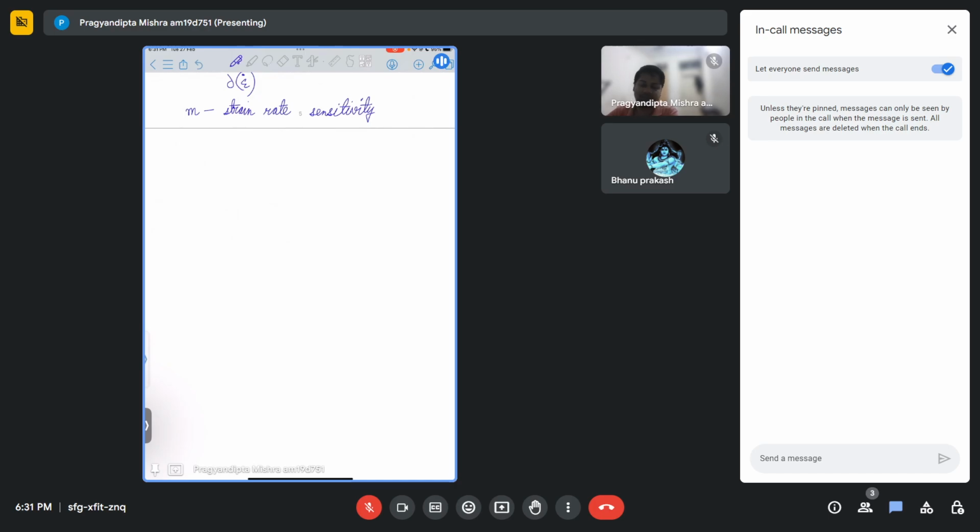If you want to write this in relationship form, this would be sigma is equal to c times epsilon dot to the power m. Now this c and m are different from whatever we saw in the flow stress equation. There we saw k and n, right? They are very different from this c and m, because this relates the flow stress to the strain rate, while that was relating your flow stress to the strain value directly.